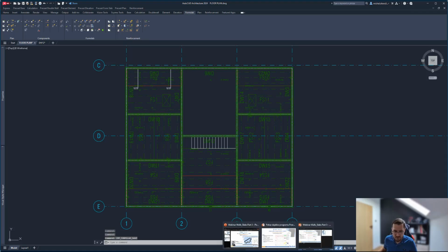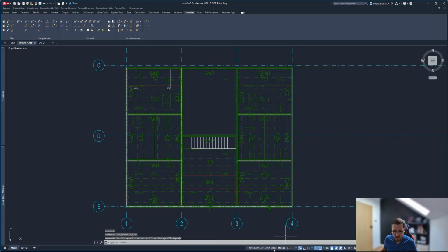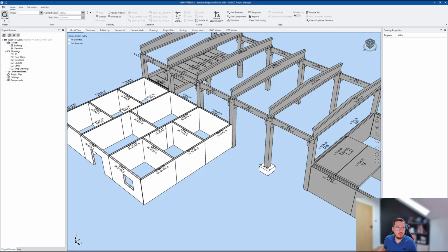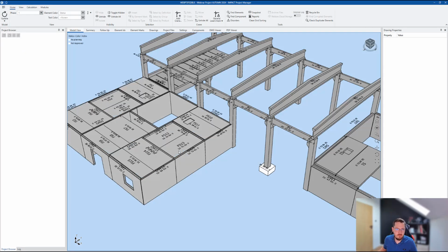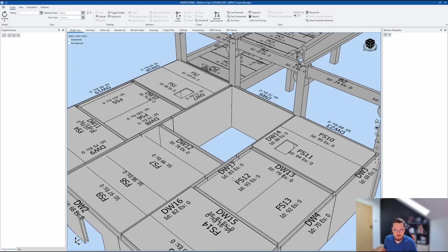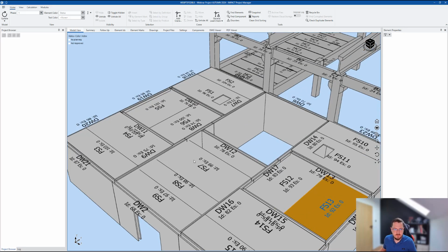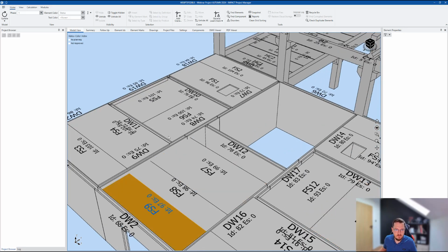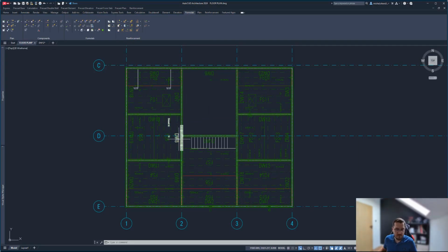So if I go into the project manager and refresh that, we have form slabs with openings. Those have an improper level, but easy to fix. Definitely easier to fix. So we'll just move those by 200 up. That's also very good, to be able to check that.